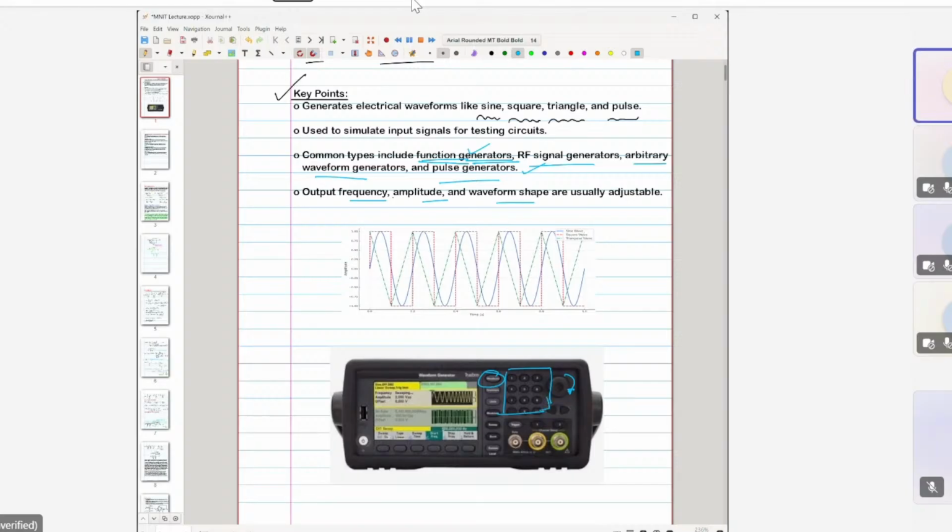signal generators do also provide this type of numeric keypad. So here you can enter the magnitude and enter the value. And there is, say, a third one, the unit. So here this unit means you can change, suppose you want to give it some in millivolt. Then no need to turn this knob so much to get to the millivolt. You can directly press this unit and change between volt, millivolt, like that.